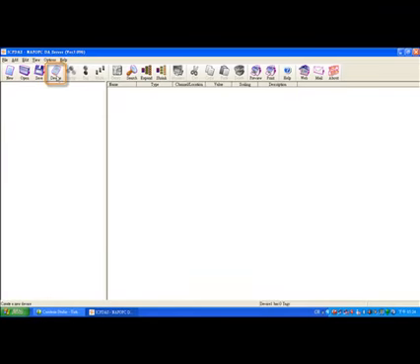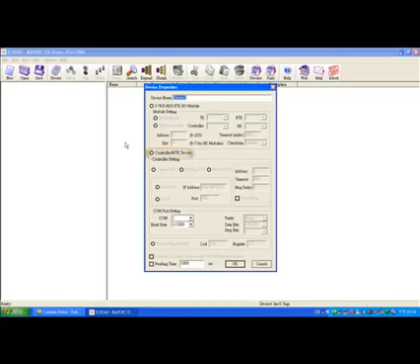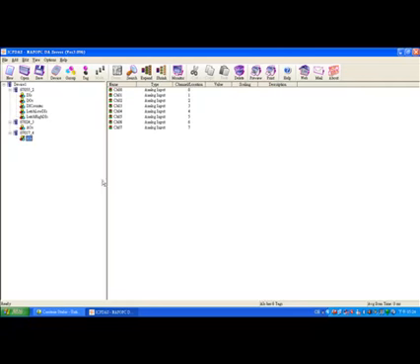Click the Device button above. Configure the settings according to the video. The IP address is that of the WinPAC. The port is the port number of RPC Server. Then, click the OK button so it can scan all the modules and IOs on the WinPAC. Then click the Monitor button above to get the values from the IOs automatically.